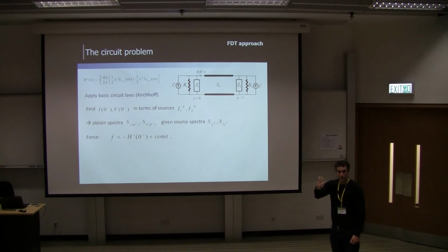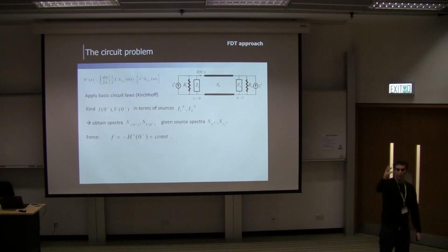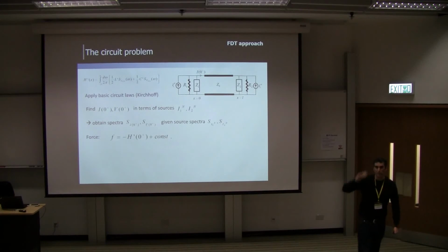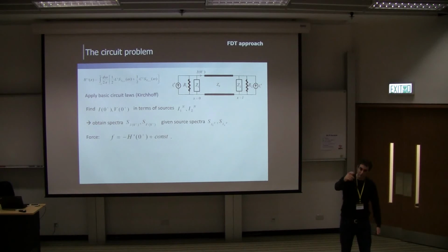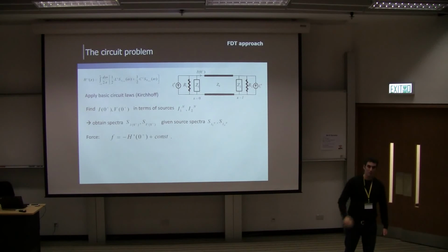What happens in a metal, in a perfect electric conductor? For the transverse field, you have a 0 boundary condition. This is why, in order to satisfy this 0 boundary condition, you have to have a reflection which is the opposite in sign, but the same magnitude. No, it's the same. It's well known in transmission line theory. Maybe it's like second or third year electrical engineering. You know the reflection coefficients of all of these things. It's -1. For a short circuit, it's a perfect magnetic material.